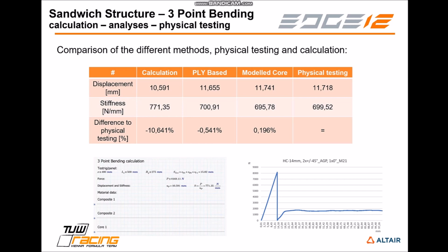Keep in mind that the testing rig also has a stiffness, so the results from the tests aren't necessarily the results that you are looking for. You need to subtract the stiffness of the testing rig from the results as well.